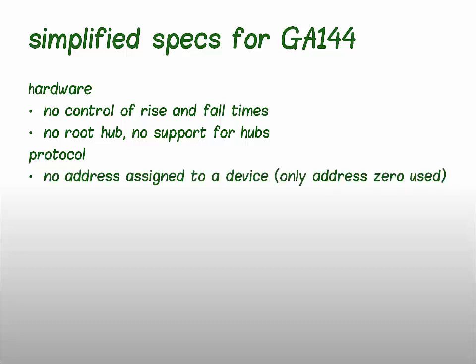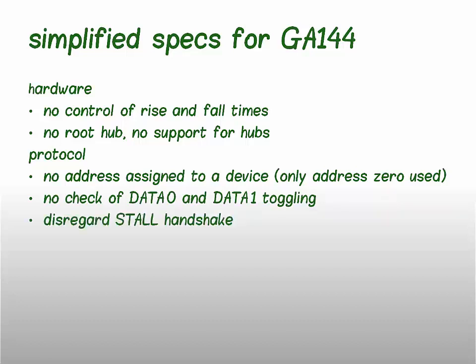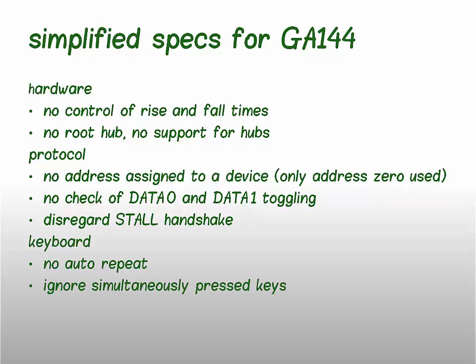Also, we never transfer more than 8 bytes of data in a single transaction. Thus, data 0 and data 1 toggling is not checked. We also disregard stall handshake. Finally, the keyboard controller does not provide for auto-repeat feature, and it also ignores simultaneously pressed keys except for Shift key. Let's have a look now at hardware part of the project.